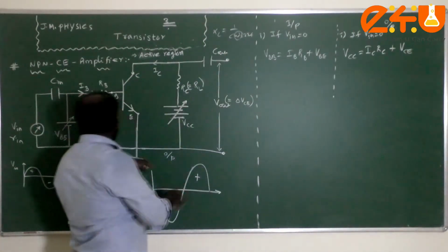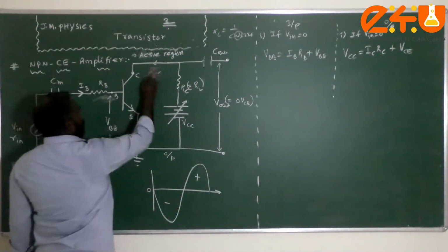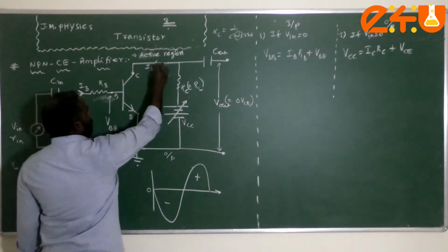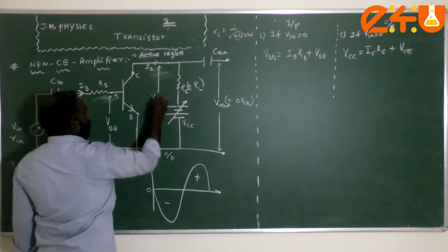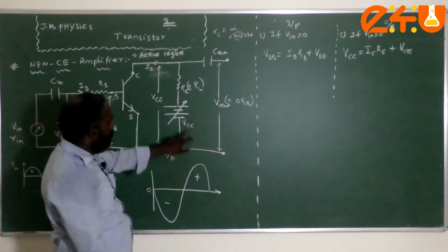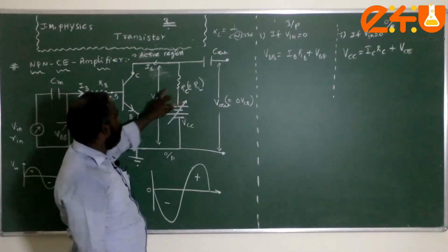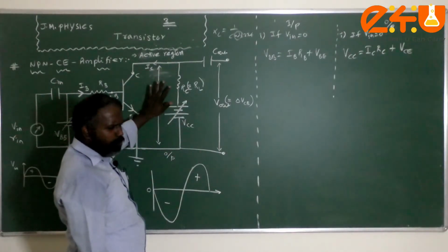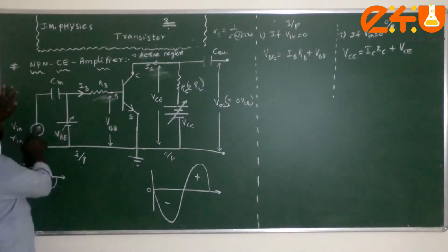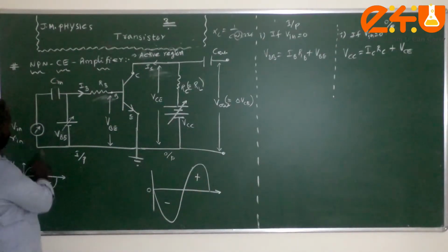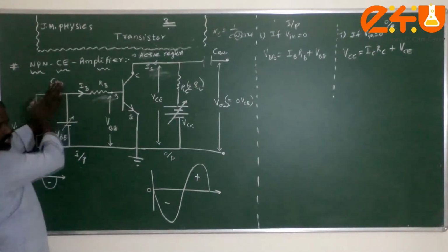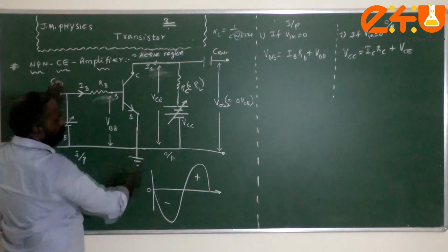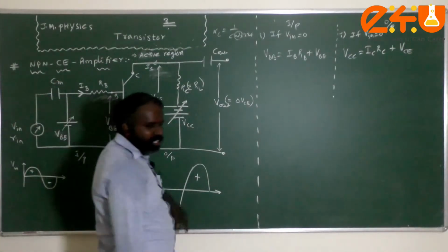Yes, we know that VCE, we already discussed. This potential difference between collector and emitter is called VCE. So applied voltage equals the sum of the voltage across the remaining part of the output part, when this input signal is considered to be 0. That means if this is 0, then this part is ineffective in the circuit. So only this branch of the circuit exists or is active.